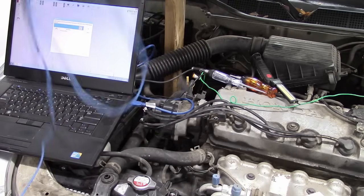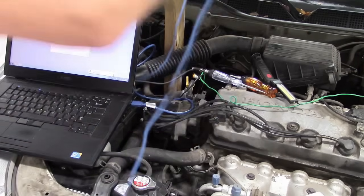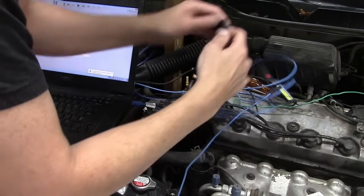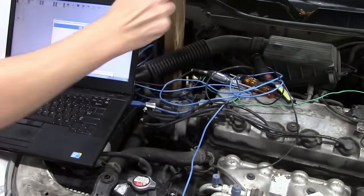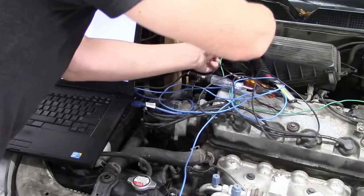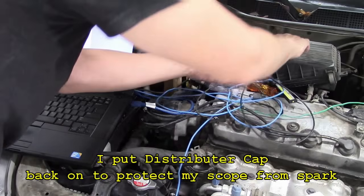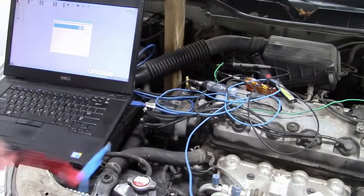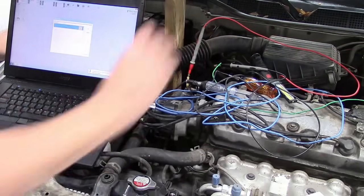So I've got my lead wire, which will go right to channel 1 in the PicoScope. You've got a lot going on here right now. This looks like a mess. What I want to do is get a negative lead, and that's going to go to ground. Hey, I've got a nice ground wire right here. As a matter of fact, my spark wire will serve as a ground. And then my positive lead, where is that? My positive lead is going to go right to that ignition signal.